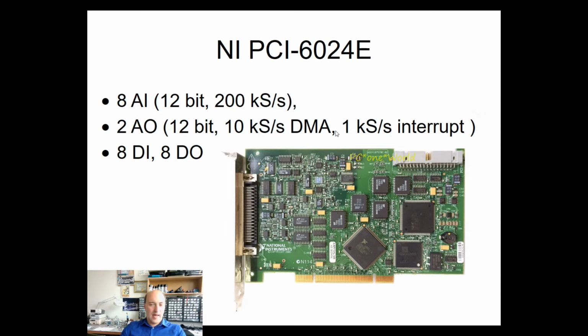And then the DMA controller that runs on the card, it's programmed in one of those chips that you see on the board, takes the samples and puts them directly to the memory of your computer, to the pre-designated space. So it has a direct access to the memory, and hence it's significantly faster. It does not require any interaction from other components in the computer. Now in Simulink, as we will run it, we will use this slower mode, the interrupt mode.